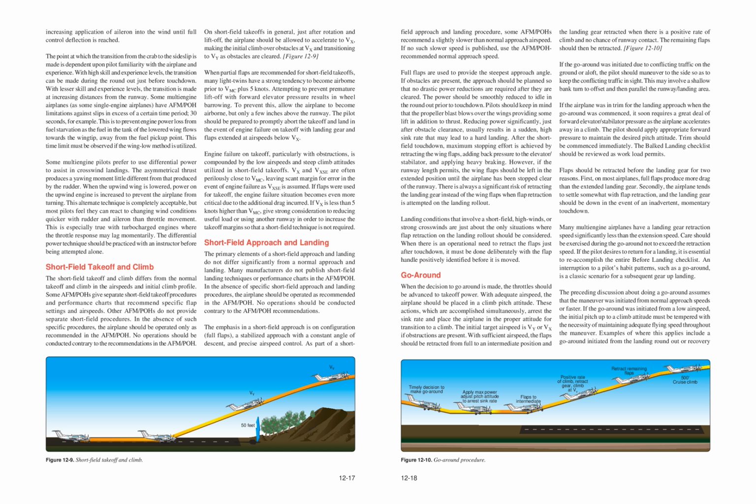Short field approach and landing. The primary elements of a short field approach and landing do not differ significantly from a normal approach and landing. Many manufacturers do not publish short field landing techniques or performance charts in the AFM/POH. In the absence of specific short field approach and landing procedures, the airplane should be operated as recommended in the AFM/POH. No operations should be conducted contrary to the AFM/POH recommendations.